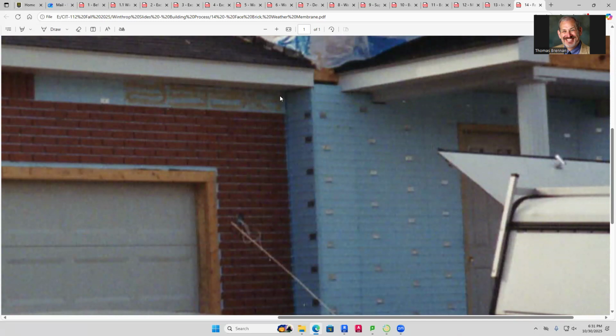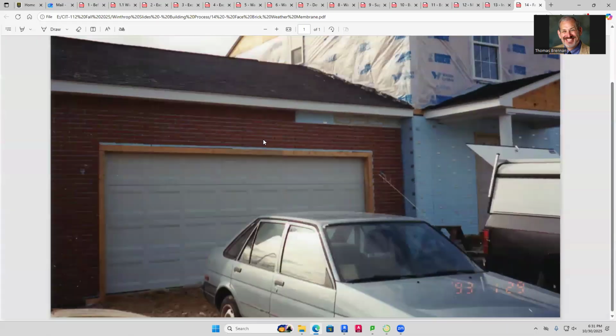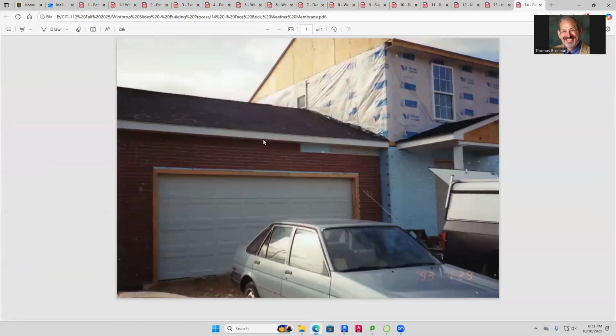So you actually put in this adhesive, you snap the bricks into place into these grooves. And then later on, I mentioned to you what we did there. And that was to actually fill in those grooves, I had to mix up mortar in a grout bag, a big, literally it was a chef's cake decorating bag. You fill it right there and you squeeze on this thing. I stand on the ladder all the way to the top and just kind of do all those joints right there. Strike it with a pipe.